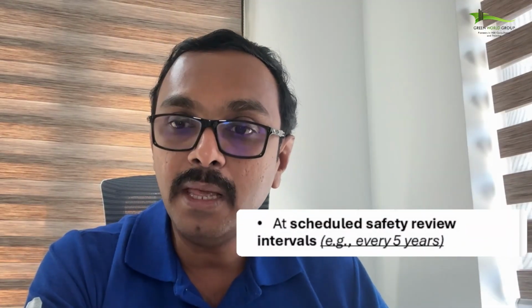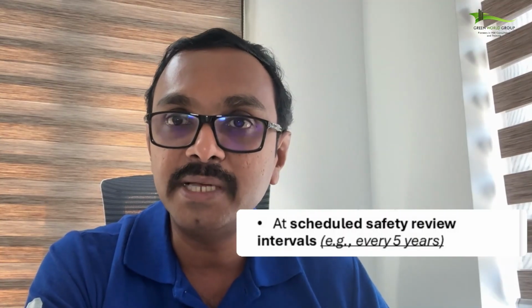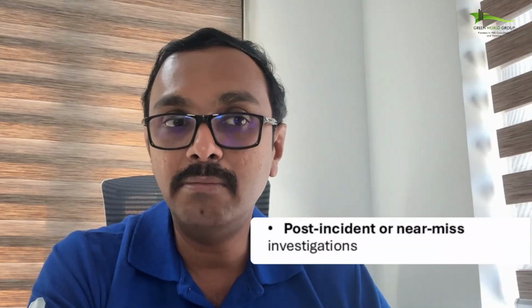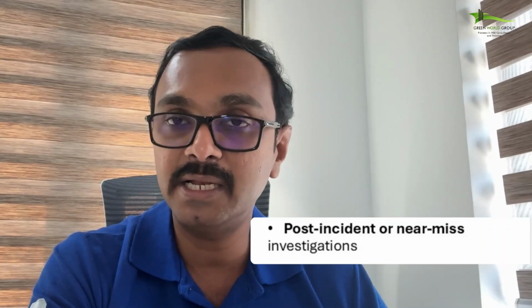In addition, HAZOP audits should also be scheduled on a periodic basis, which I would say is about once every 5 years. Please also understand that certain countries may have a different set of regulations, where this duration can be less or sometimes even higher, but 5 years is a good, suggested one. We also conduct a HAZOP following an incident, a major near miss, or an accident, to help understand what went wrong and how to prevent it. So these are the situations where we have to conduct a HAZOP audit.